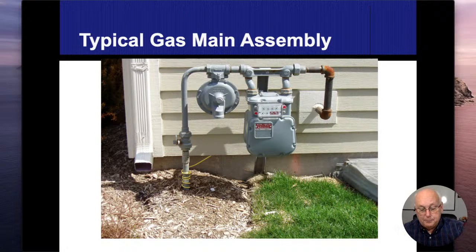So we come back in, 4 psi, the pressure reducing regulator will lower it down to 1/4 of 1 psi. Then it comes to our gas meter. These dials on the gas meter is what I was talking about. You timed as those go around when you do the gas timing chart. And again, you can find that up on our website. And then it comes up through here and then into the house.